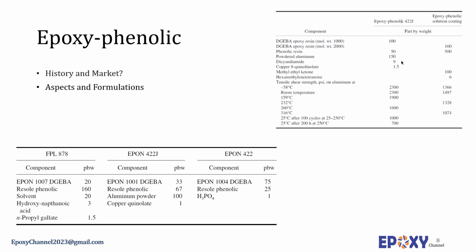Epoxy phenolics were developed in the early 1950s and they were the first high-temperature epoxy adhesives to become commercially available. The first epoxy phenolic adhesives were developed at the Forest Products Lab (FPL) as a result of research aimed at high-temperature military aircraft adhesives. Epoxy phenolic adhesives were developed primarily for bonding metal joints in high-temperature applications. Their first major application was to join major aircraft components.